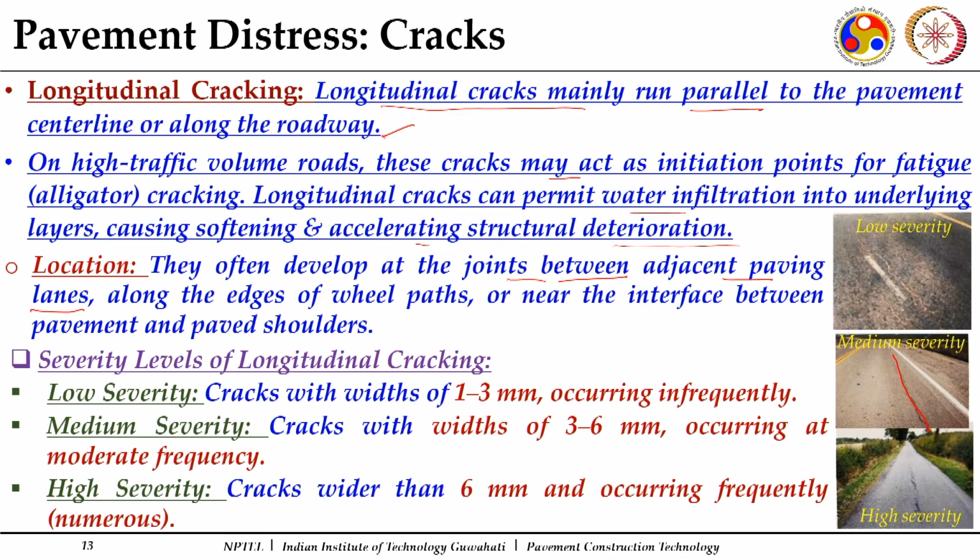Wherever that joint of the asphalt mats comes up, that can be a place where these longitudinal cracks can be observed, or along the edges of the wheel paths, where you are observing this particular one, or near the interface between the pavement and the paved shoulders.